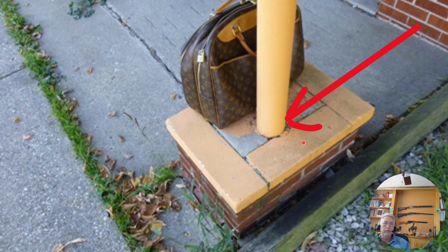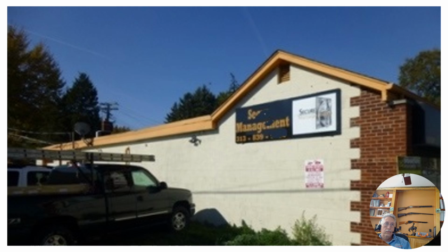Okay, so we took a long shot of the front of the building, this commercial building, and then we go in and take our close-up shot. A light that didn't work, so we put that in the report. Then we hit a pole over here, a metal pole, sort of a stanchion pole. We do it like we would inspect a stanchion pole in a basement, right? Connection at the top, make sure it's secure. Then you look at the bottom to see if it's rusted out, because they rust out over many decades. Here in Detroit, it takes about 80 or 90 years for one of those to rust out. That was about it on the front, not much going on there.